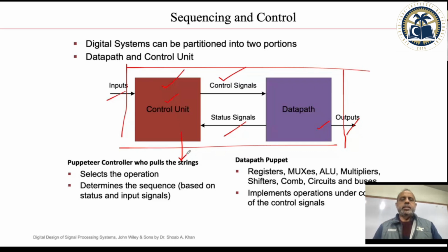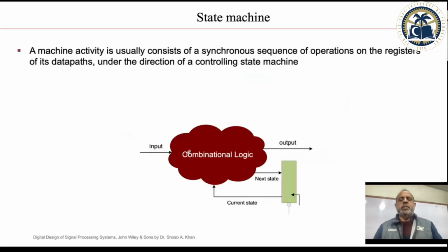your architecture design is. And then we said the controller is a state machine, and a controller would always be in this form. It will have a register which will hold the state of your design at any instant in time. A combinational logic takes input based on the current state and the input, and decides what the data path should do next.